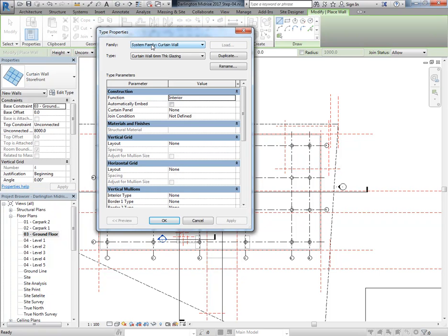They're hard coded, so essentially you've got 3 different kinds of wall families. You've got basic walls, curtain walls, stack walls, and that's it for walls. And that's all you need. You don't need any others. Anything else you can make with model in place. So it's actually a good setup. And then to make your own kinds of walls, you're not making new families, you're just duplicating types.